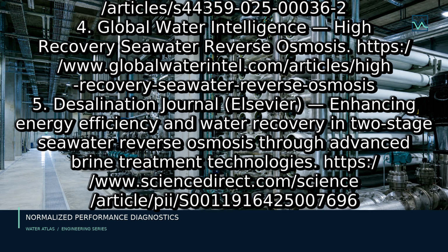To maximize freshwater output, modern design increasingly turns toward high-recovery seawater reverse osmosis, pushing recovery rates from traditional 40 to 45% levels to 60, 70, or higher via multi-stage configurations. Every drop of permeate produced leaves behind an equivalent volume of concentrated brine. Managing this reject stream is one of the most critical environmental and engineering challenges of our time.